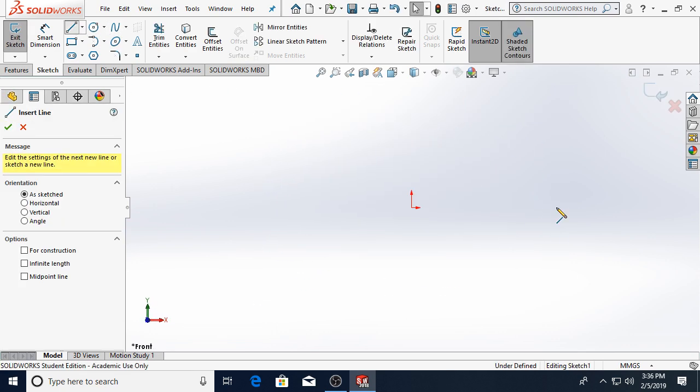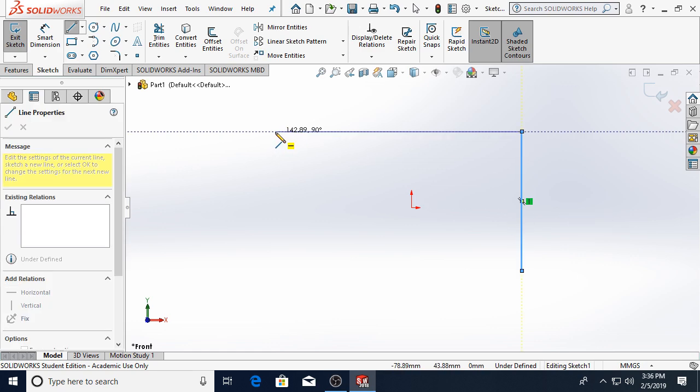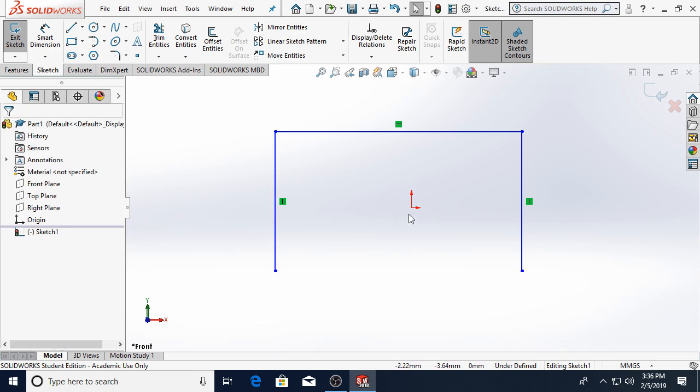So if I were to, for example, create the handle like this, so that the endpoints were below the origin, I don't have a plane corresponding to these endpoints. So the closest I could get would be to draw a sketch on the top plane that awkwardly intersected like half of this leg, and then we'd have to create 2 extrusions, one going one way, one going the other way. This is the sort of situation where keeping in mind where your cardinal planes are, i.e. positioning your origin, is especially helpful.